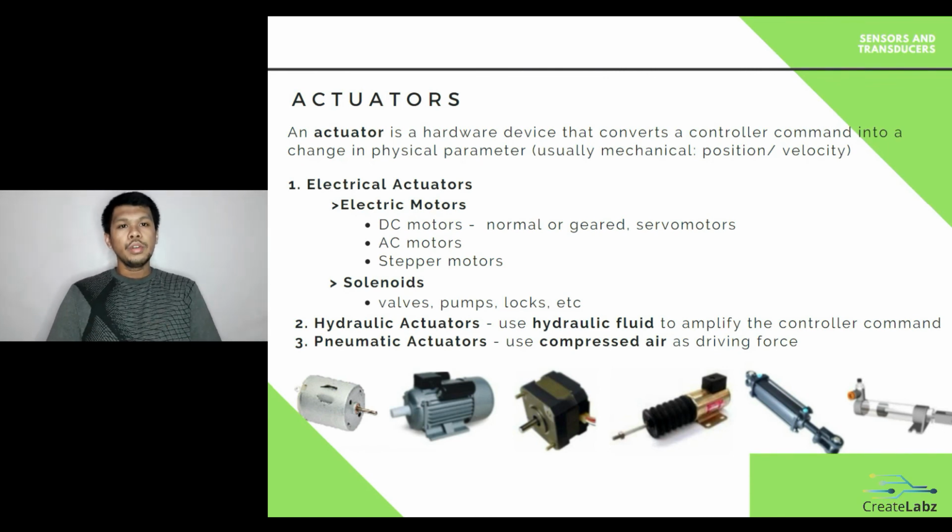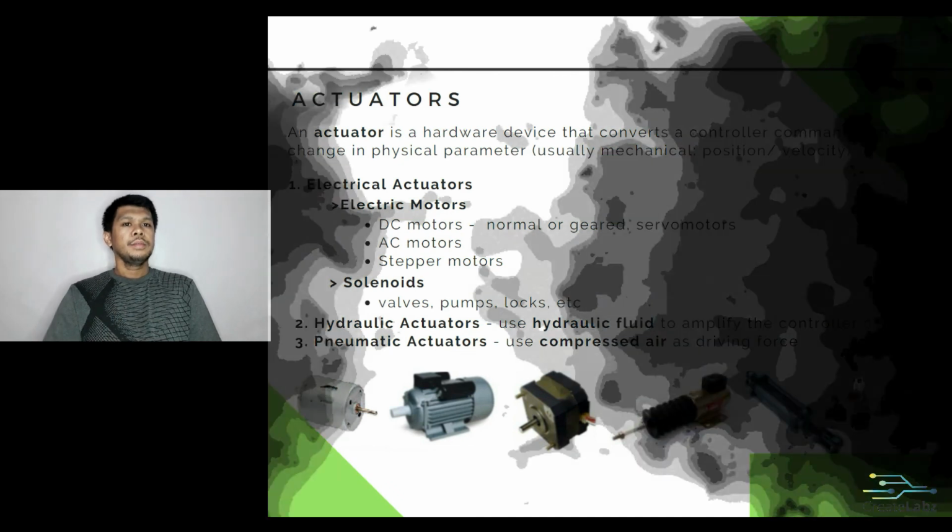Just notice the sound when the bus door closes. That's pneumatic, an example of a pneumatic actuator. Can we interface pneumatic and hydraulic actuators to Arduino? Yes, we can, but we need drivers or converters, since hydraulic and pneumatic are mostly mechanical devices and Arduino is an electrical device.